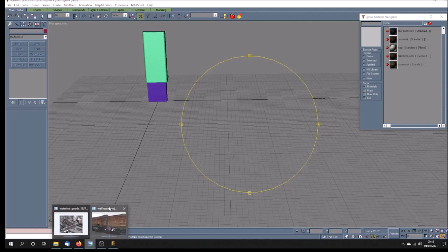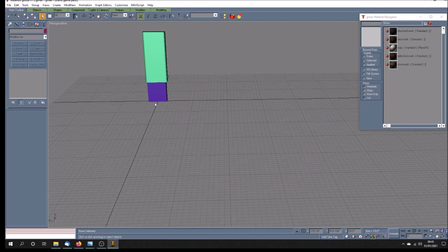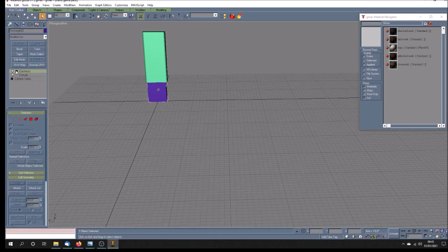Now if we look here again, let's check what we're doing. Actually what I can do is I can just reduce this block here, instead of coming from the ground up, make it 5'9", I can make it 1'3", and that will just be that bit there, because then I'm going to tuck this in here. So let's just alter this, edit the mesh, pick up those vertices, make sure you've got there, and move it up to 4'6". There we are.